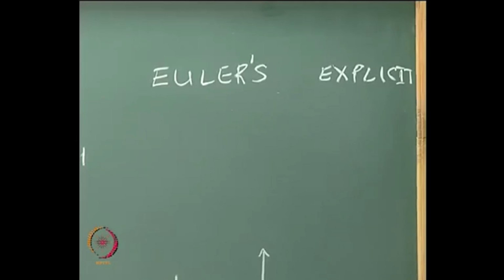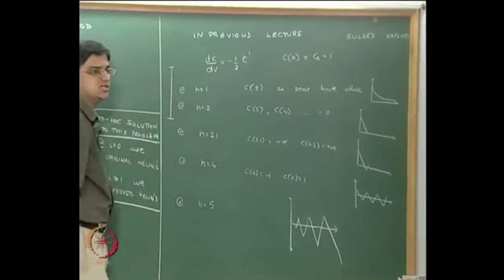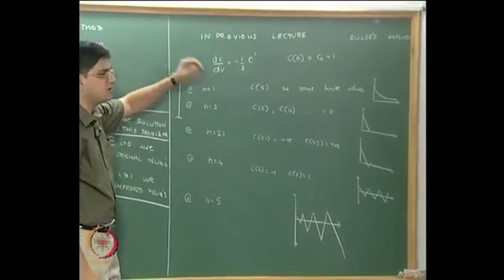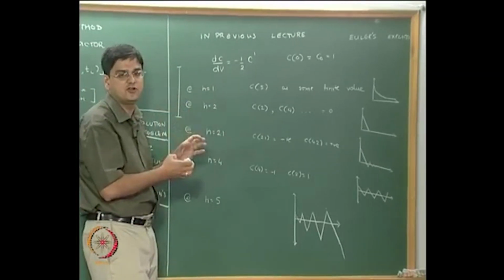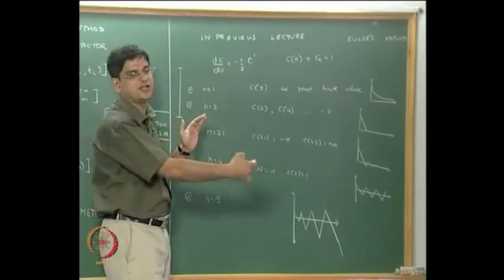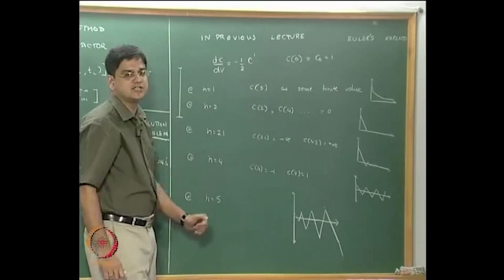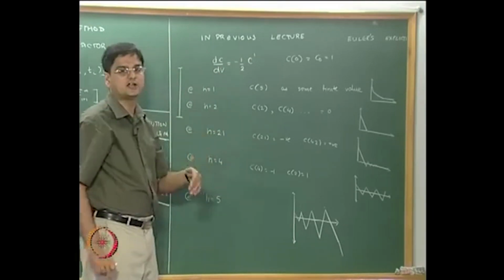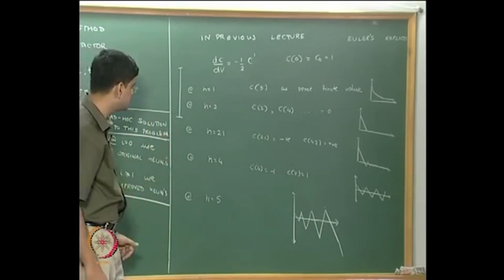Okay, so what happens over here in this range is that the solution converges monotonically. Keep in mind that this is a plug flow reactor. Physically, in a plug flow reactor, the concentration cannot go in a fluctuating manner. It has to actually smoothly go to the final steady state. That is what we will physically observe in a plug flow reactor in which any single reaction is taking place.